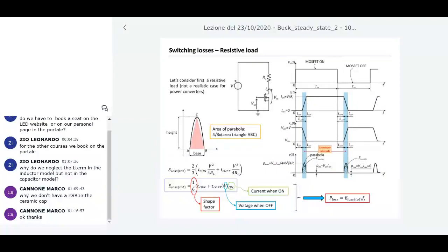So we cannot evaluate any more in this course, in the examination, etc., the power dissipated when the switches are off. For now, it is zero. Okay, so we are interested in the power when the transistors are on, the conduction losses, like the average power computed previously. And another important parameter is the power dissipated when the switches are commanded to turn on and turn off, so in the interval of time in which they change their status, which is called the dynamic losses or switching losses.